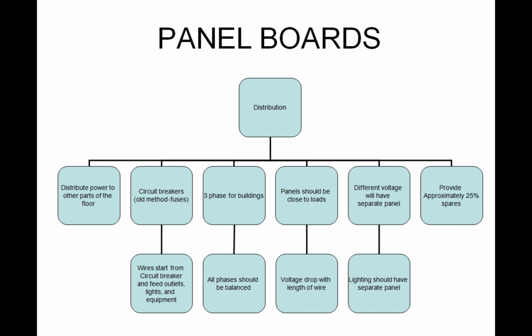Every panel distribution board, you should probably have spares. We talk about having about 25% extra space for more circuit breakers. The reason we do that is because you never know when you have a building that you'll need to upgrade at some point to meet the code. If code changes, if there's more access, if you expand the building, you want to make sure that each of your panels has a little bit extra in it so that you can accommodate small changes.